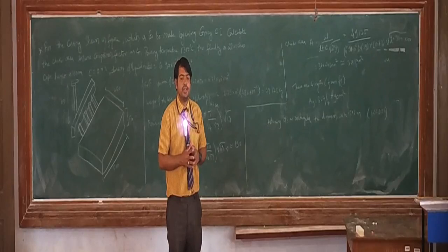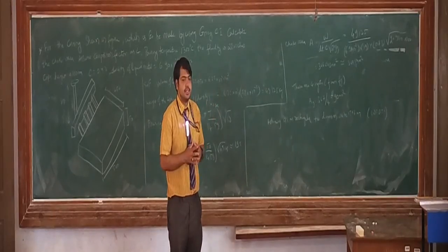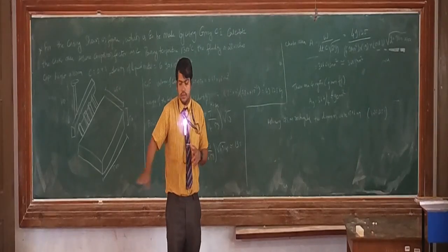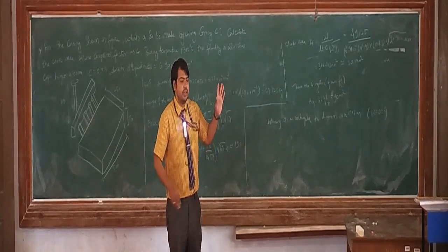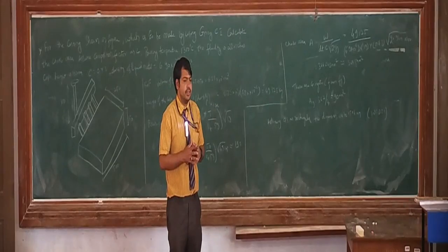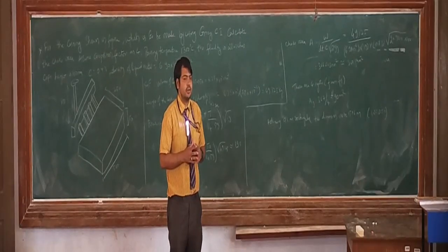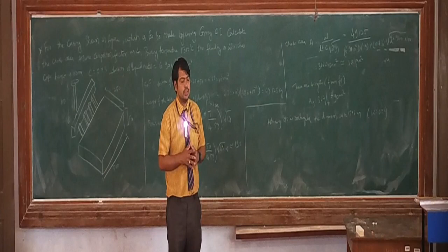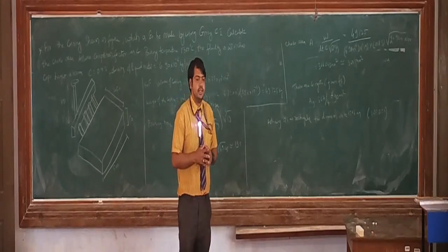The most important thing in solving such problems is the units. If units are given in millimeters for the casting, then convert all the other constants or all the other values in terms of millimeters only. Kgs, grams, those unit conversions are very important. So if a unit goes wrong, then completely whatever values you get will be wrong. So please concentrate on the units.